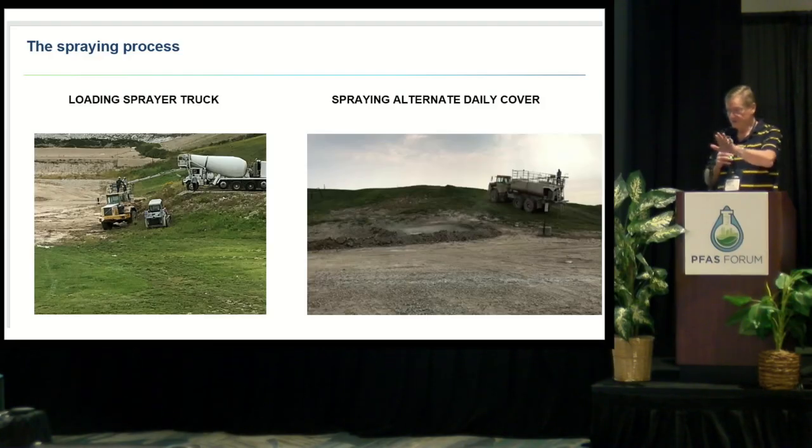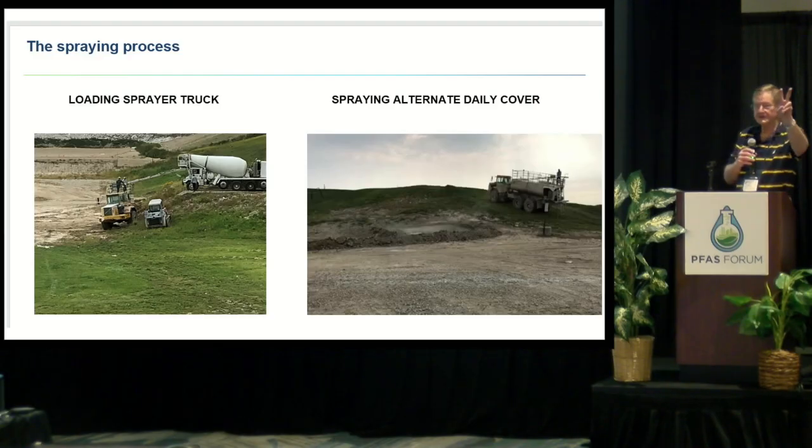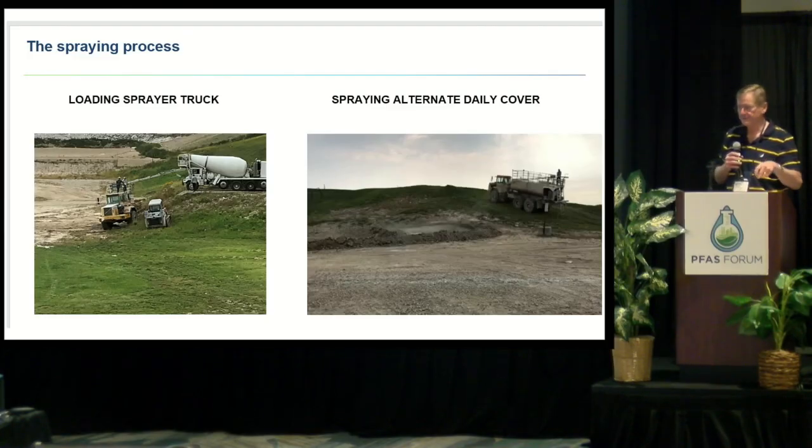And so the first couple, there's two little areas here where we had two different mix designs. I had started off with 42 mix designs and narrowed it down to two that seemed to work the best on bench tests encapsulating the PFAS in the concentrate. So you'll see two here.